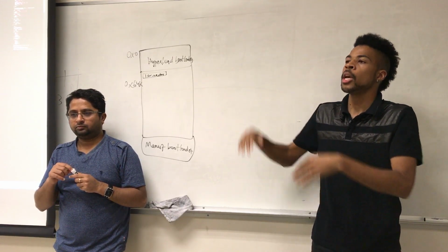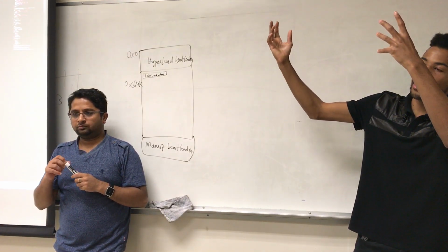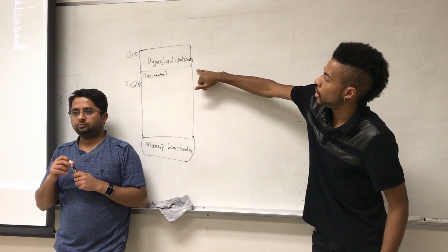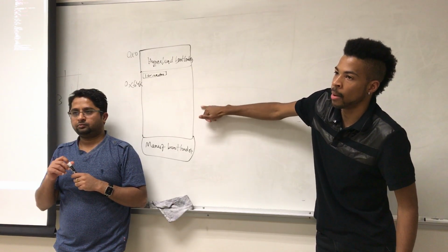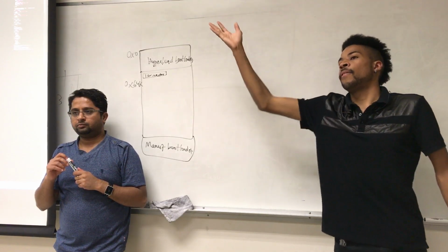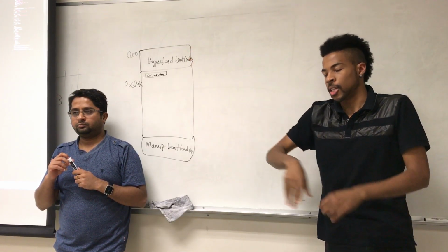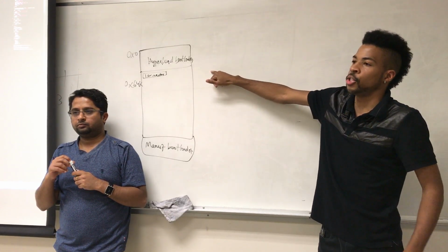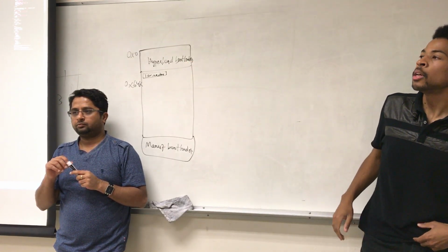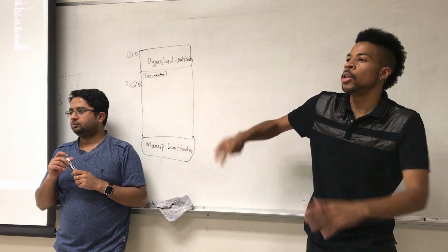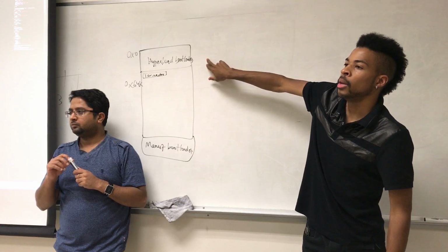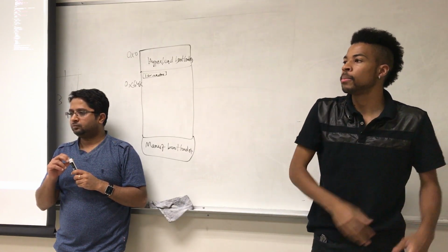Once everything's kind of established, when you start reading in data from serial, it starts dumping it into flash. It starts writing your file. But usually a good 64K in. If it sends out an FF and doesn't get anything back, which is usually when you see all the LEDs light up, then it jumps to your application, and then that's when everything else here runs. So this part is all after that. Nothing that you really can touch inside of the code that we write here has anything to do with hyperload. That's just another program.